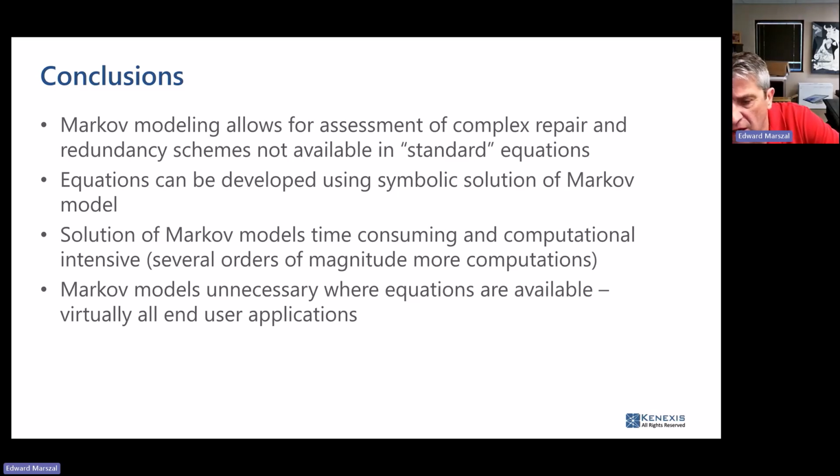So with the Markov modeling, a lot of what was just brought up there actually isn't in the Markov models themselves. Things like the site index is a factor that is intended, using some qualitative hocus pocus, to try to modify your failure rates as a function of how you treat your devices at your site. So a site that has really good maintenance practices is going to have lower failure rates than a site that doesn't have really good maintenance practices.